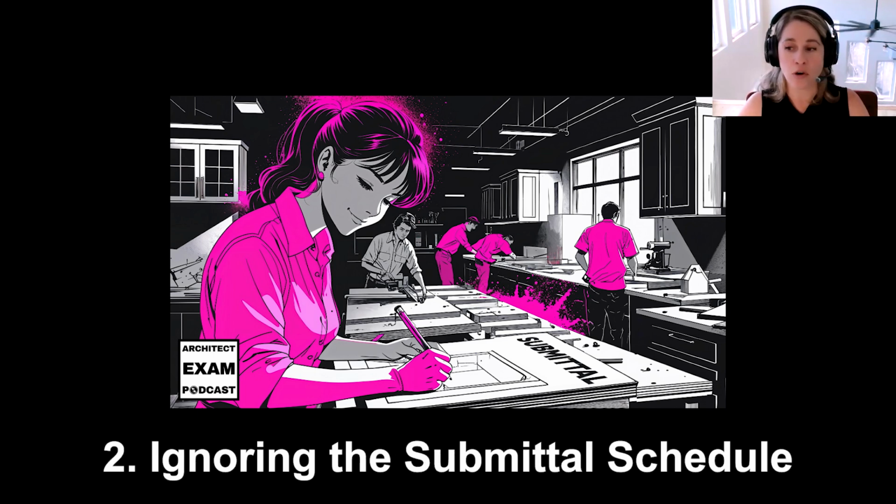Or you may receive or share a submittal that ignores the submittal schedule, which is a critical mistake. I see it a lot if you just completely miss a deadline on a submittal or you submit something out of turn. This can just lead to a snowball effect of delaying a project. For example, a late submittal on structural steel can delay the entire building envelope coming together because you need the structural steel in order to build your building. Think of submittals like a domino effect. If one falls late, everything gets late behind it as well.